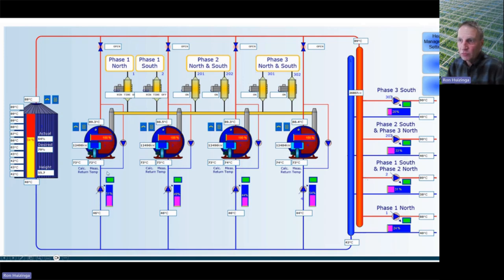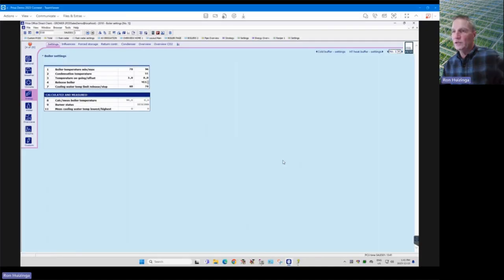So if this water gets too hot, if this gets up to 60, 70 degrees, that condenser is going to get too hot and it's going to trip and say my water temperature to my condenser is too hot, my CO2 air is going to get too hot, and it trips out and gives you an alarm. So what we like to do is stop it before that happens. And how we stop that is by looking at the bottom two sensors of the buffer tank.